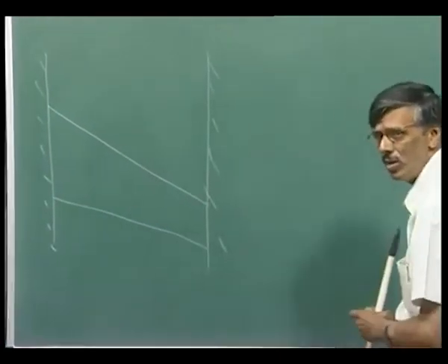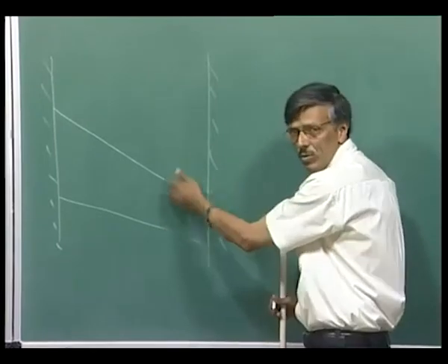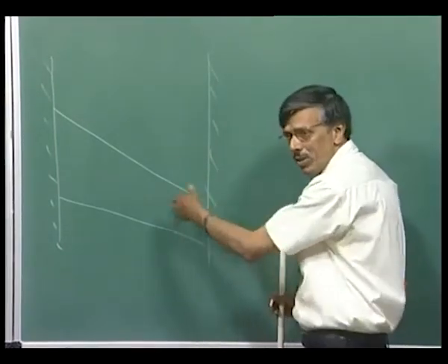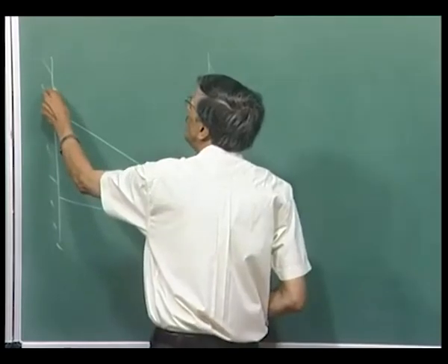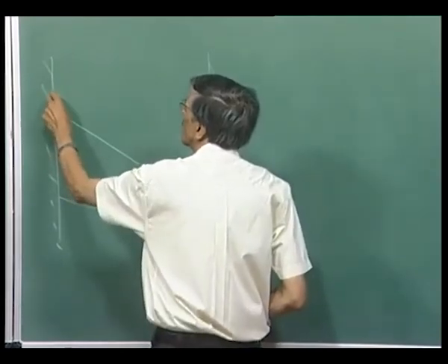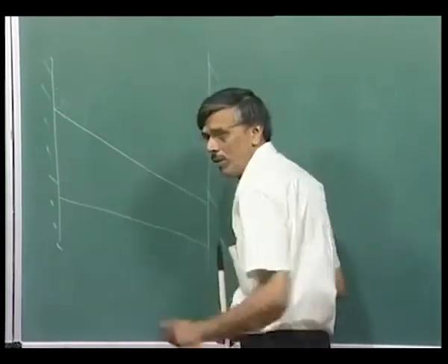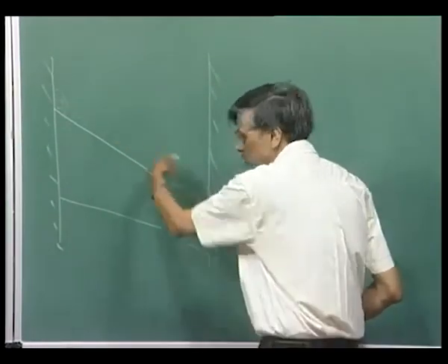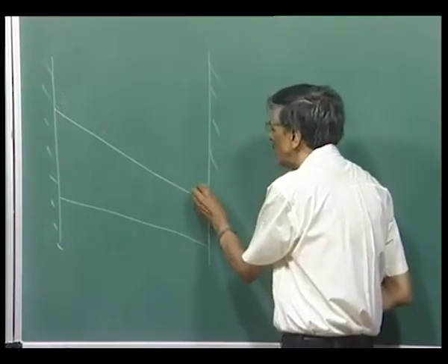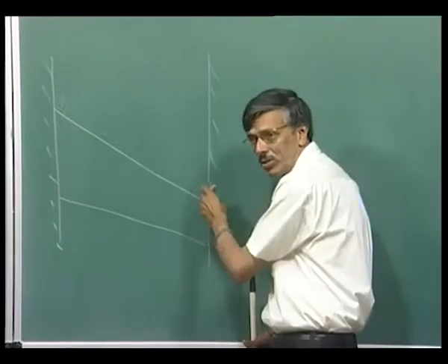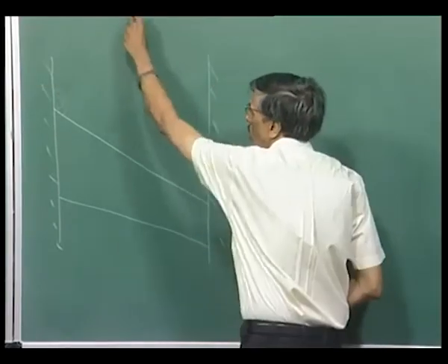The idea is not to have any stiff vortices which will affect the flow in the near vicinity, so you do it in a wall to wall fashion. And then of course, you will have vertical structures forming there that migrate along the spanwise direction. You would also have similar vertical structures created here, corner vortices here.